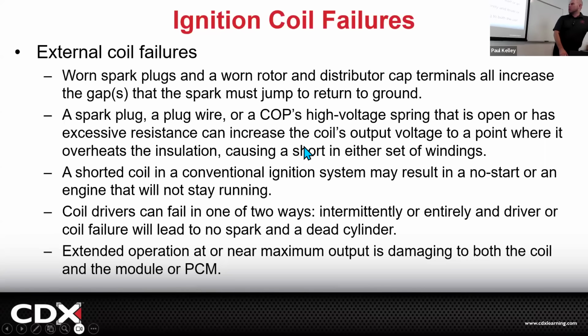And then of course we get a shorted coil, which would mean it's going to short internally. So we've seen where the coil is arcing outside, but they can also arc inside because your coil is bolted to something, and usually the thing it's bolted to is metal. So if the coil shorted, it could be sending its secondary voltage right through the short. It won't spark. It'll just send all of its voltage through the short. And that would be either a misfire or a no start.